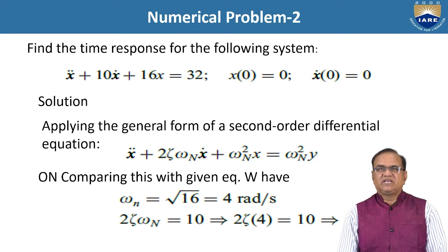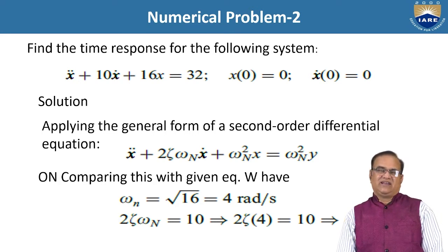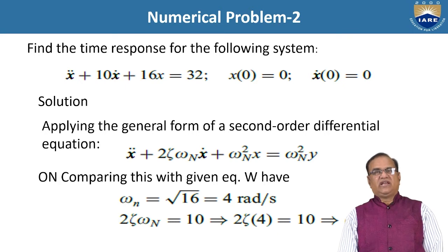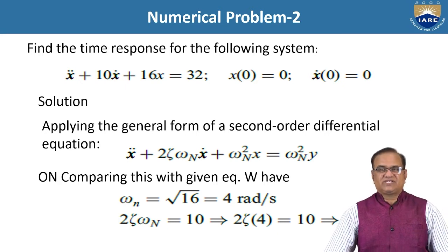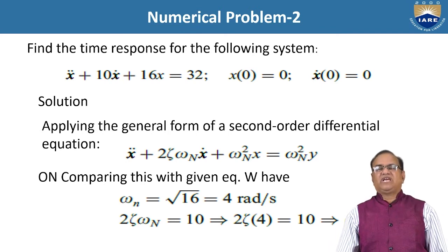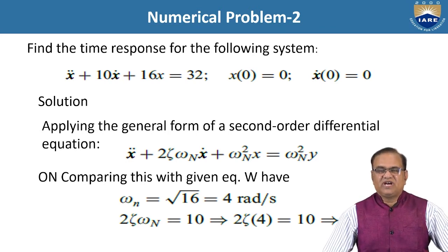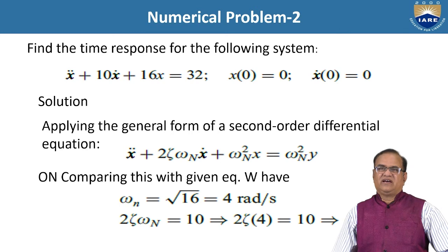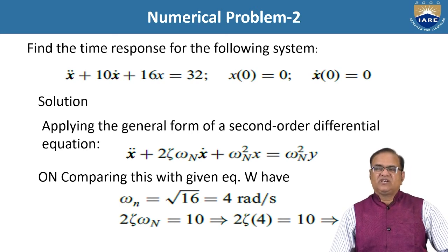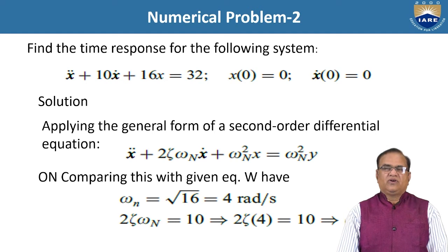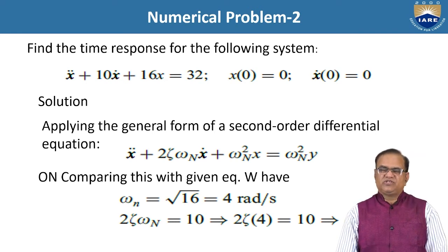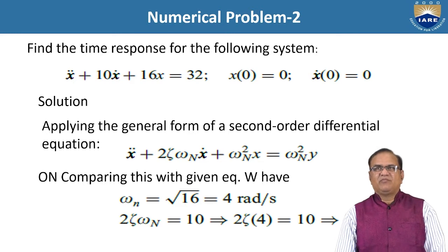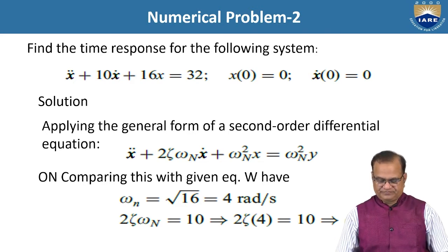To have the dynamic stability, we have seen that omega n and zeta should be positive, and also we have to ensure that it is a short period mode or the phugoid mode. We don't want much time for the aircraft to come to the stable condition. So we should make sure that the damping should be sufficient so that it reaches its equilibrium position without taking much time. That we have to ensure.